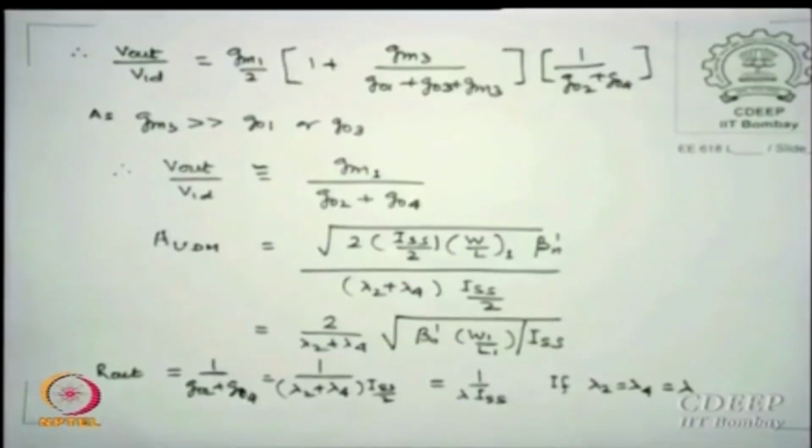So you also should imbibe this, because there are 4 kinds of amplifiers which we can use, all of you have gone through this earlier: output current, input voltage; output voltage, input current; input voltage, output voltage; and input current, output current. So 4 types. It is called transconductance, transresistance, current amplifier, voltage amplifier, all 4. Okay, is that clear? So this V by V only tells input is voltage and output is also voltage.